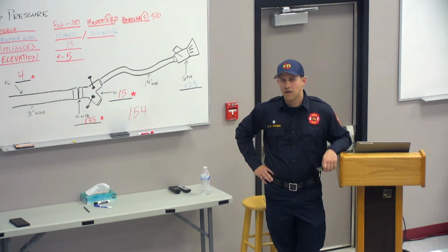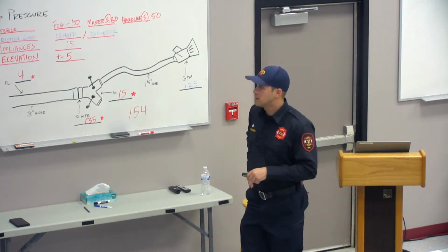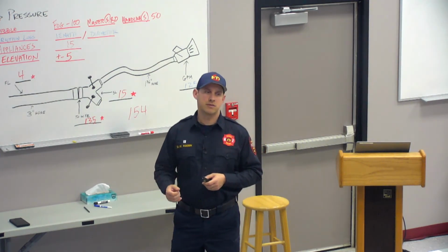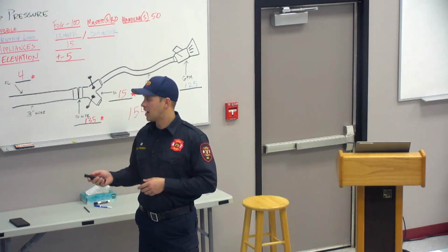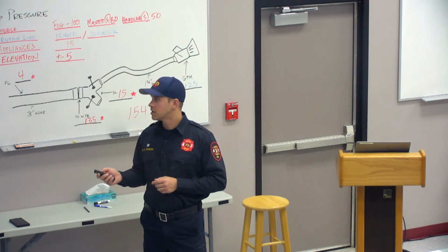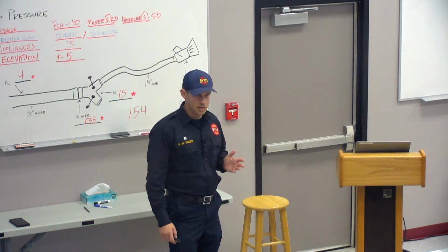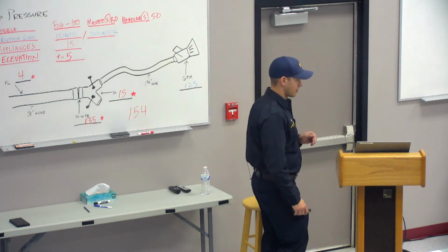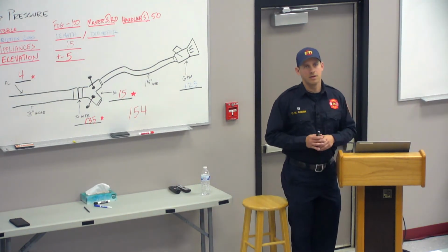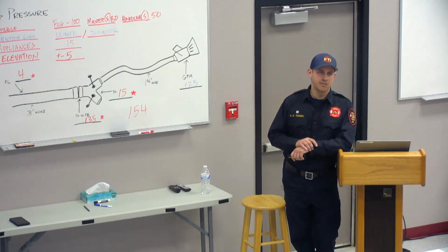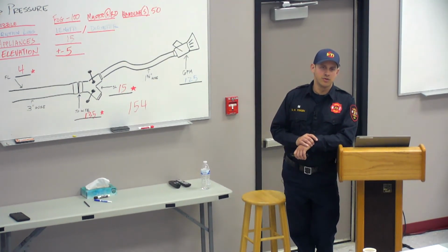Okay. If not, let's say we have positive water. We open our intake and we got, right off the bat, and we're in pump, let's say 200 PSI showing there, at throttle. We open up a line and we see a 10% drop. So we go from 200 to 180. What does that tell us?